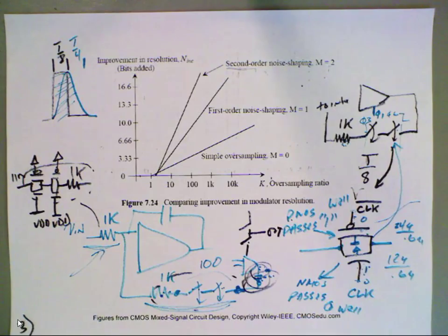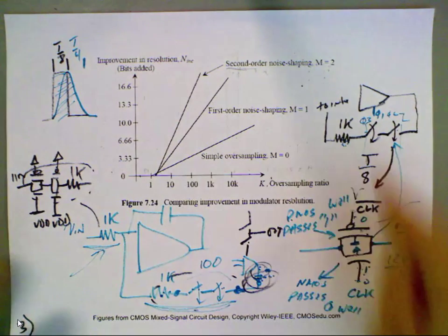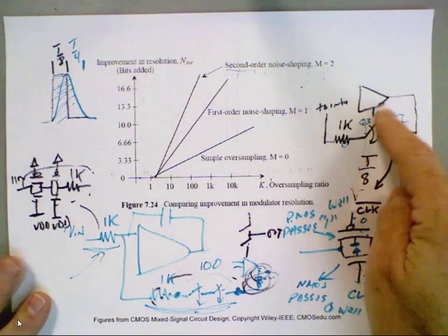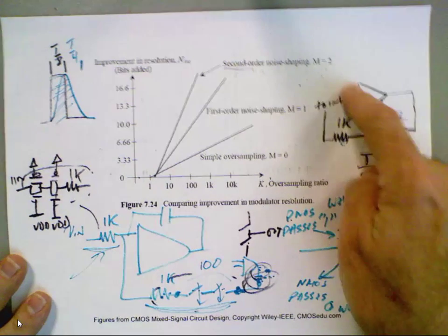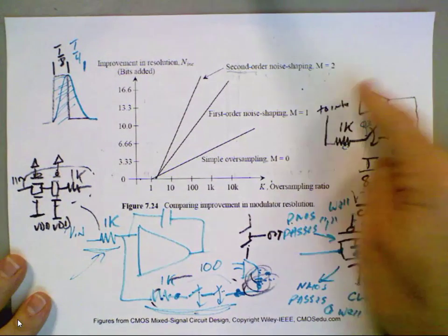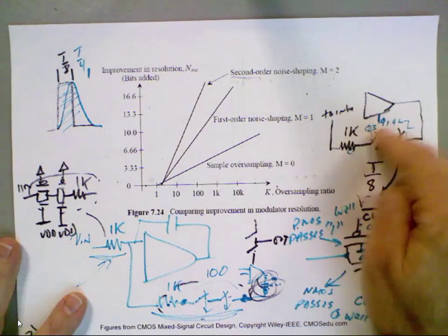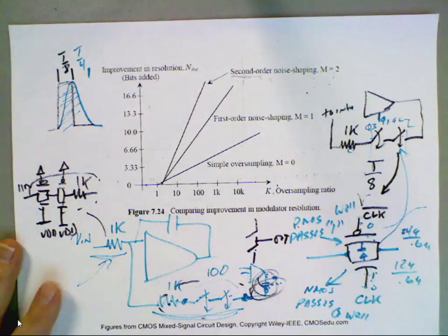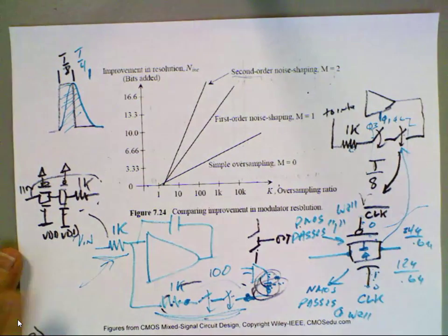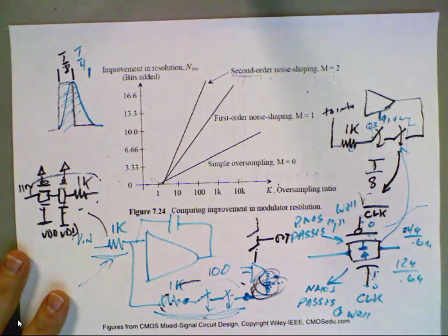Does that make sense? So you do it for high speed so that it will work fine, with the problems of comparator delay. So you're conservative when you select these. But if you go slower, then that comparator delay may not be an issue, and you can make these a little tighter and closer, and then your SNR would go up. Yay? Nay?